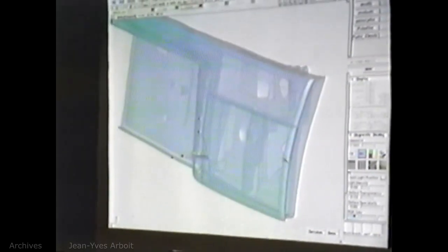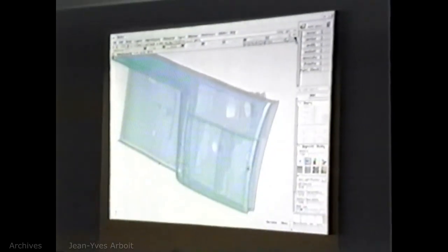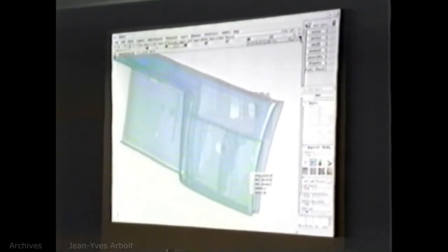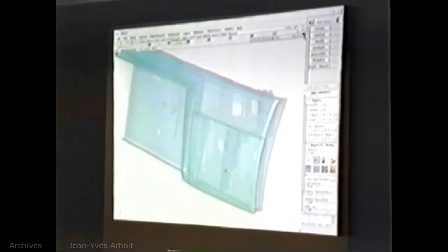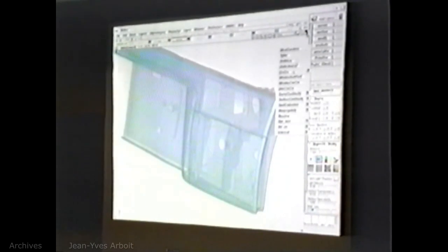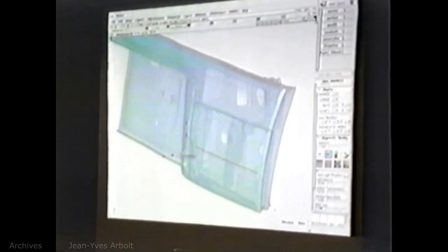But you can take a single surface. If I pick, let's see, that surface there, and then turn on the dynamic section, you can also say, give me some geometry wherever I cut that section. I just hit the geometry button. That leaves a section behind, so I can move it up a bit more and cut another section. Or I can ask for curvature too.